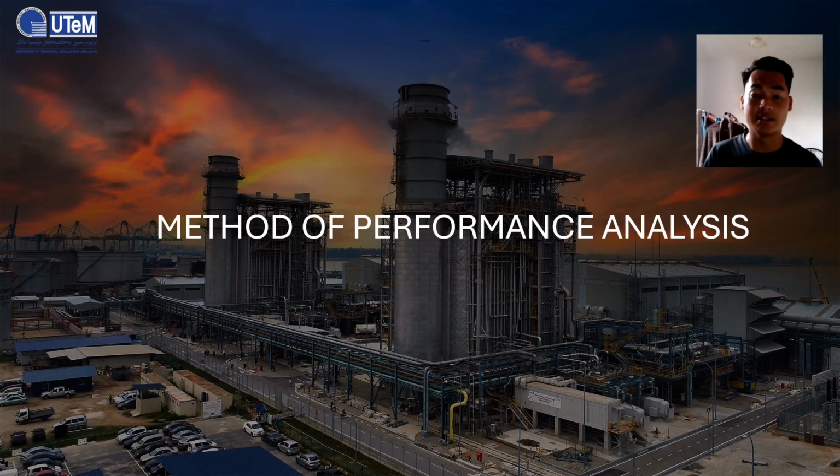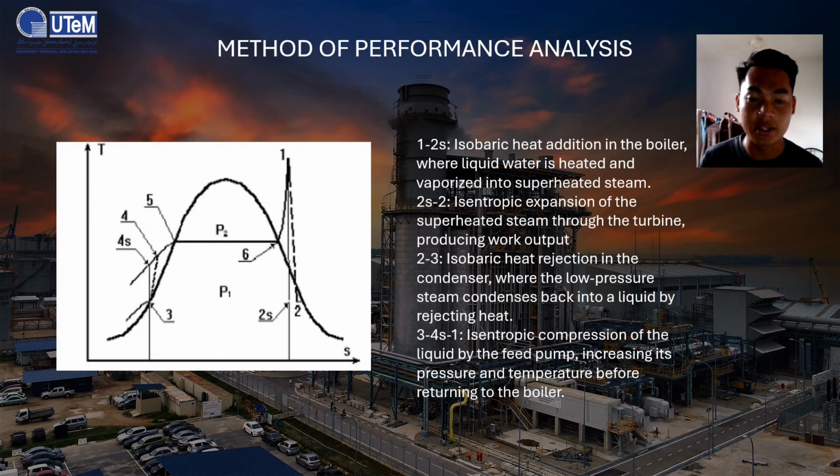Method of performance analysis. The first figure is the TS diagram for a Rankine cycle, where 1 to 2S is isobaric heat addition in the boiler, where liquid water is heated and vaporized into superheated steam. 2S to 2 is isentropic expansion of the superheated steam through the turbine, producing more output. 2 to 3 is isobaric heat rejection in the condenser, where the low pressure steam condenses back into a liquid by rejecting heat. 3 to 4S to 1 is isentropic compression of the liquid by the feed pump, increasing its pressure and temperature before returning to the boiler.